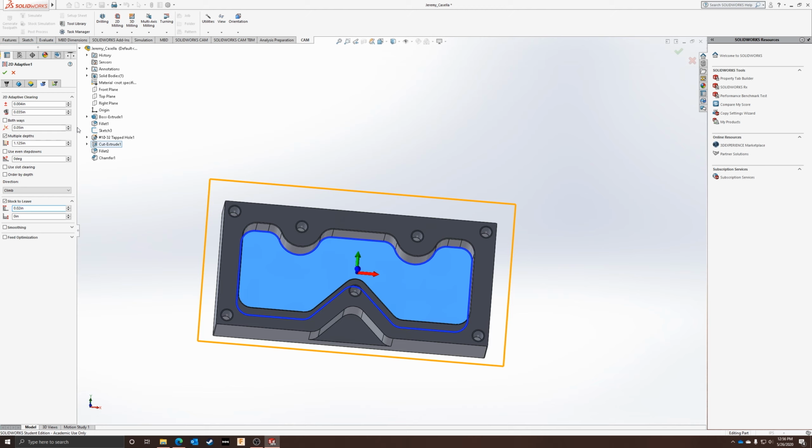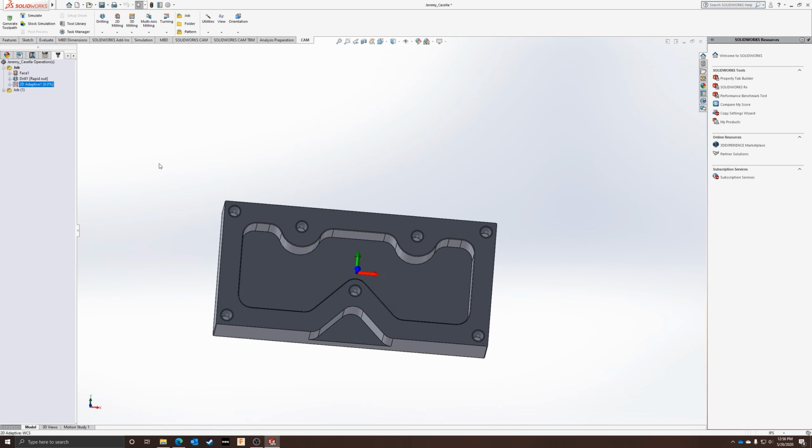Now, that's all you need to do. Remember, always set your engagement, so your optimal load. Always set minimum cutting radius. We want to drop that so it's actually below what we're doing. Something decent, that's fine. And then multiple depths, state your flute length. These two things, and then sometimes this, are important. Don't worry about linking. Hit check. It'll now generate a perfectly optimized toolpath to try to remove material as fast as possible, and you'll see that here.